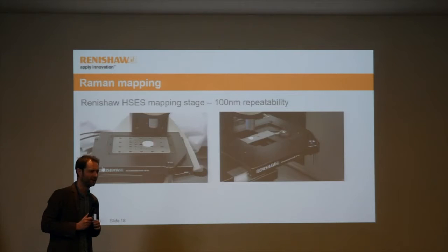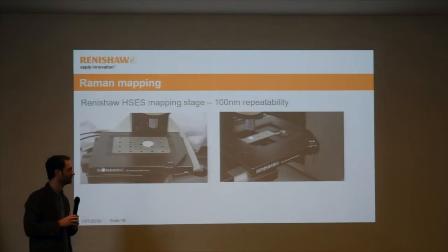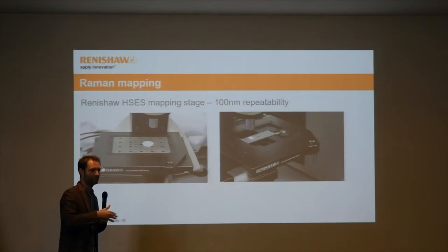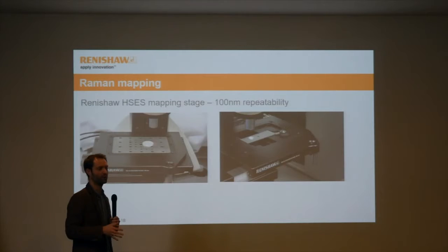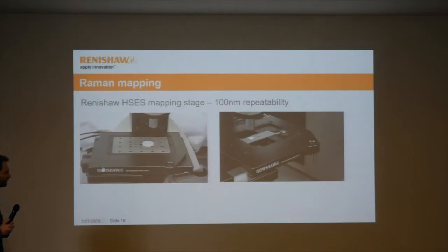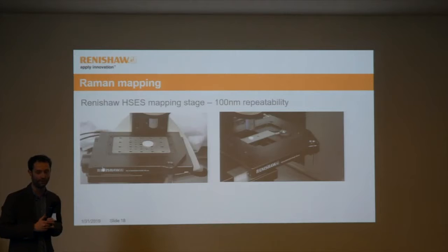Actually, we usually specify the stages by the resolution, which is actually quite meaningless. If you have a resolution of 1 micron, you know within 1 micron where you are, but you're not necessarily 1 micron to where you want to be. That would be the repeatability. Here, the resolution is the resolution of the positional encoders, while the repeatability is you are within 100 nanometer of where you want to be.